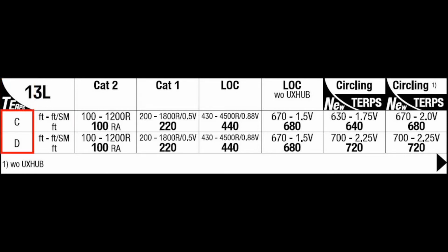The minima table will also display aircraft category or aircraft type in the aircraft box and measuring units in the unit boxes. The minima are depicted in sequence, starting from the best approach with the lowest landing minima possible at the left to the approach with the highest minima to the right.